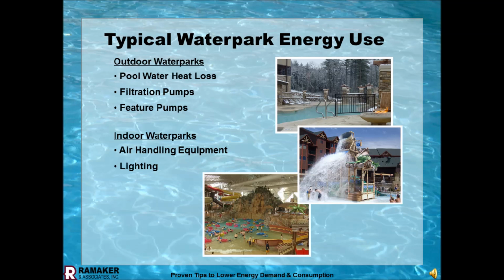So in the water park, it's pretty much understood what the energy use is. It's the pool water heat loss: evaporation, spraying water, surface area. It's the pumps, the filtration pumps, 24/7 throughout the whole season, or if you're indoor, throughout the whole year. It's the feature pumps. Do you run your feature pumps all day long, all night long? Can you shut them down? Do you need all the features running?